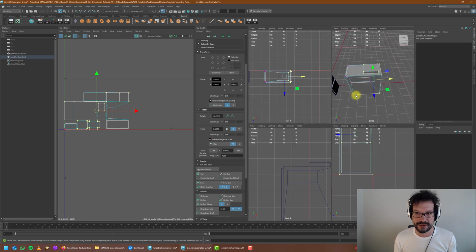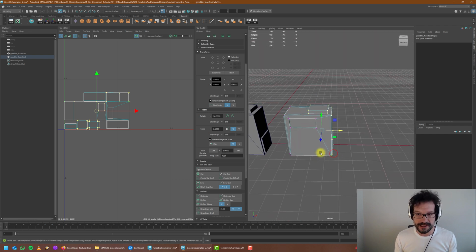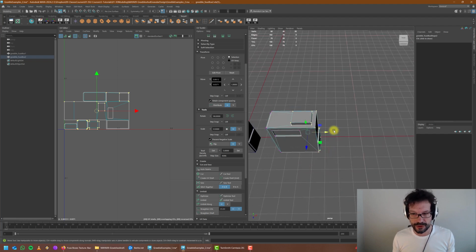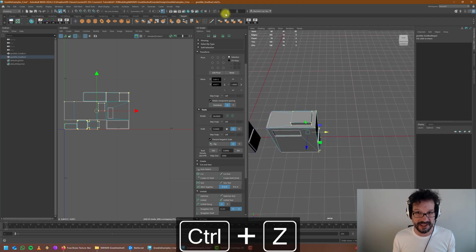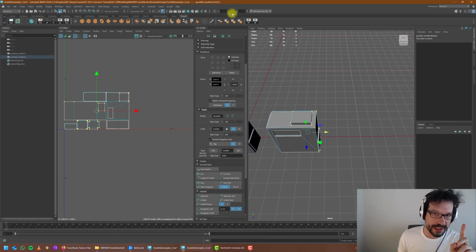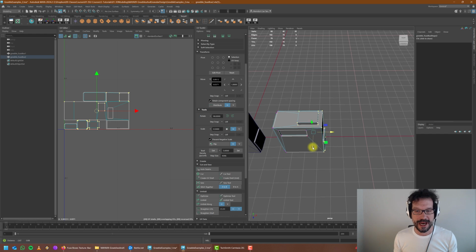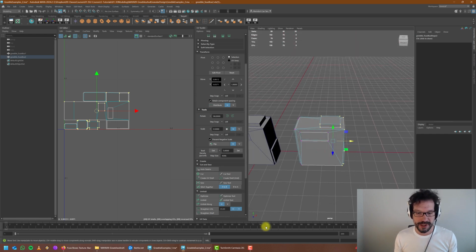Let's assume that this was approximately 30 centimeters wide. Let's create a version that is approximately twice the size, only in one direction. You can do that, and it's very easy to do. You don't even have to play around with the pivot. You can use these absolute and relative dimensional input boxes right here.